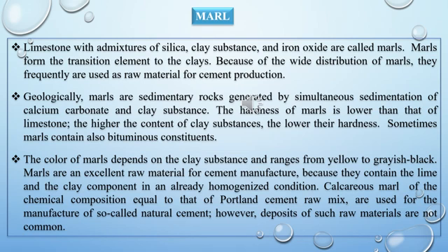Now the next point is, geologically, marls are sedimentary rocks generated by the simultaneous sedimentation of calcium carbonate and the clay substance. The hardness of marls is lower than that of limestone. The higher the content of clay substance, the lower the hardness. Sometimes marls also contain bituminous constituents.